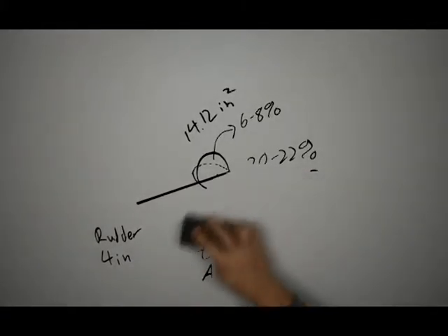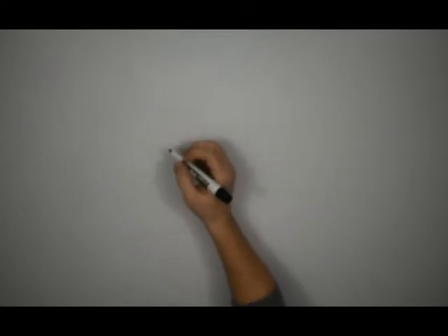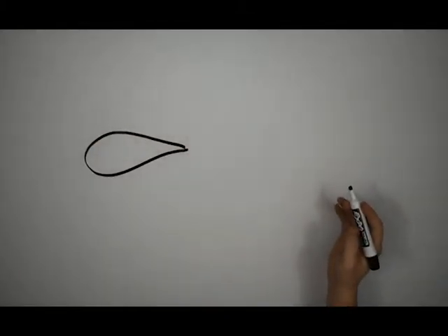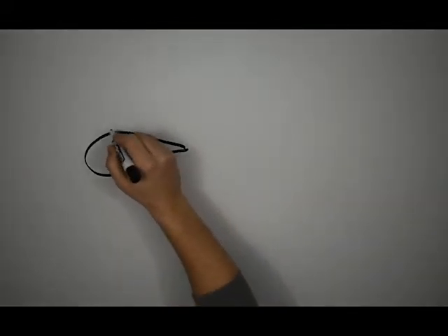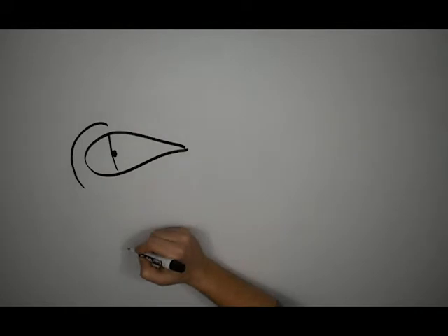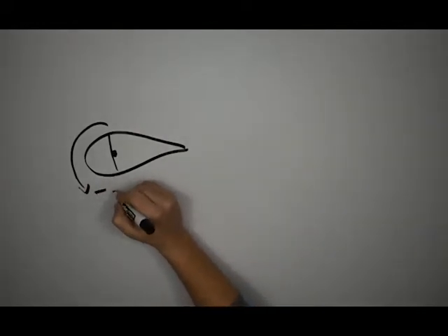Now that we have the dimensions set for our tail, let's calculate the lift and drag that it's going to be creating. In general, the tail is used to counteract the pitching moment from the main wing, along with helping to control the aircraft. So, knowing this, we're going to move backwards from using our pitching moment to calculate a force required for our tail, and then into calculating the lift coefficient we need to generate that force.